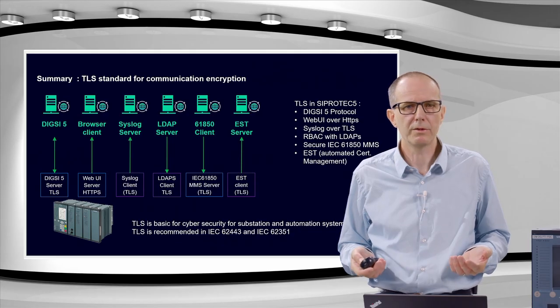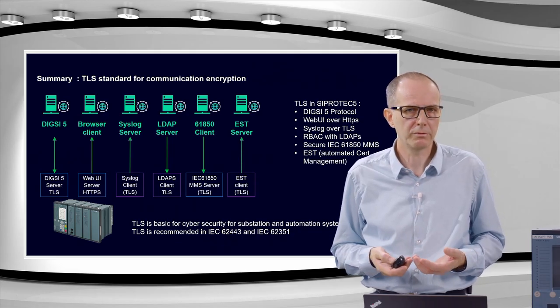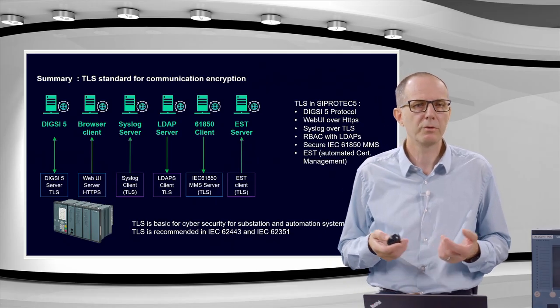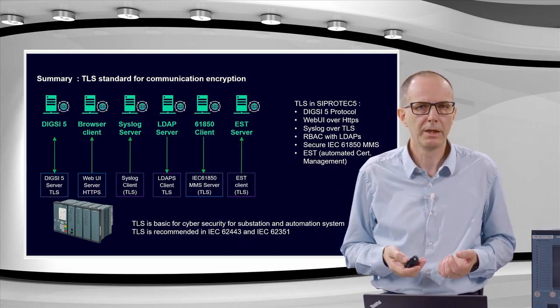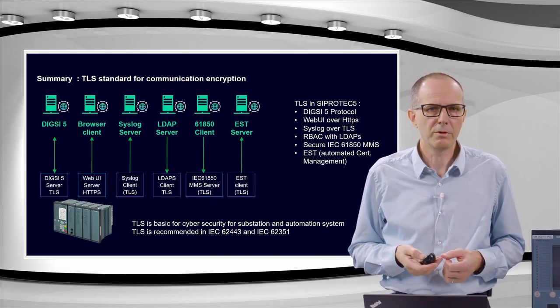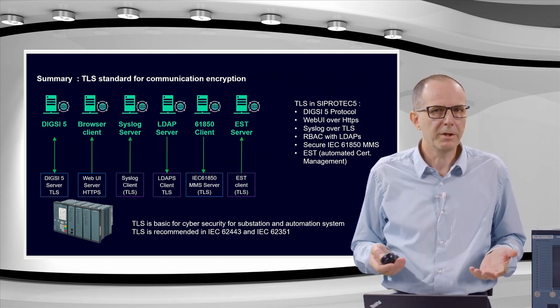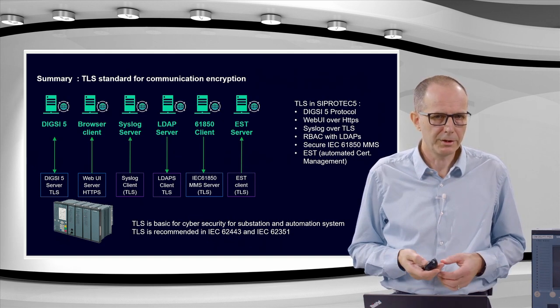We also implement the automated certificate management as recommended in the IEC 62351-9, and the protocol there is called EST, that stands for Enrollment over Secure Transport, and it is based on TLS with mutual authentication.